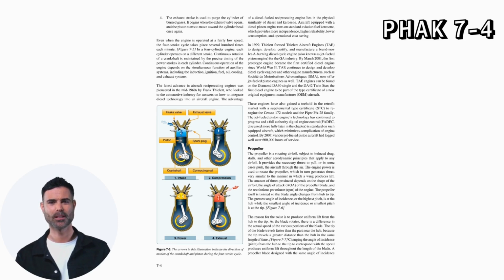Continuous operation of the engine depends on the simultaneous function of auxiliary systems, including the induction, ignition, fuel, oil, cooling, and exhaust systems. The latest advance in aircraft reciprocating engines was pioneered in the mid-1960s by Frank Thielert, who looked to the automotive industry for answers on how to integrate diesel technology into an aircraft engine. The advantage of a diesel-fueled reciprocating engine lies in the physical similarity of diesel and kerosene.